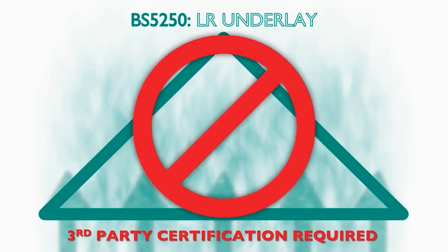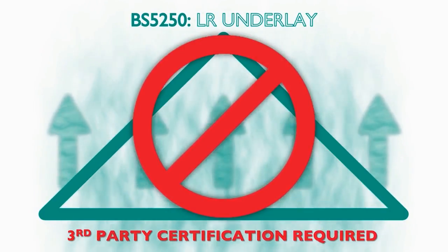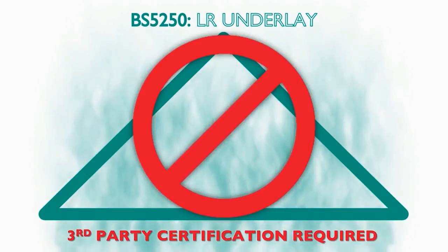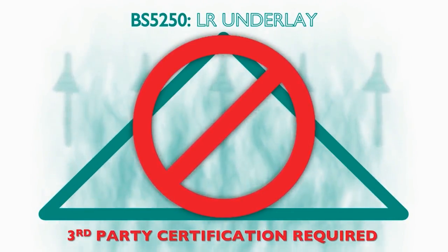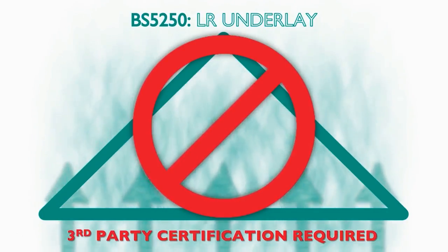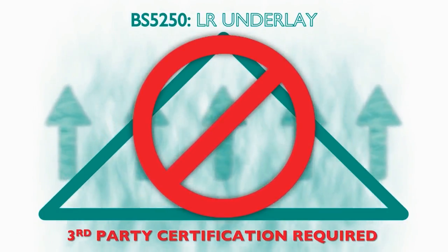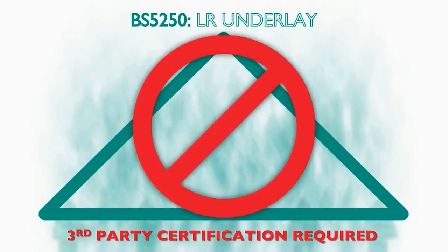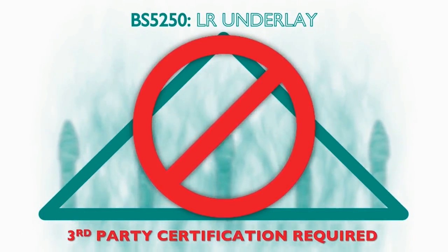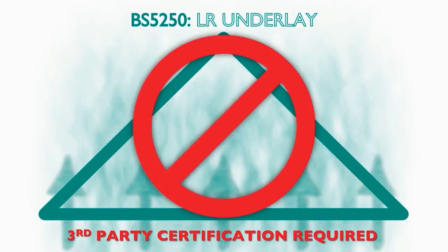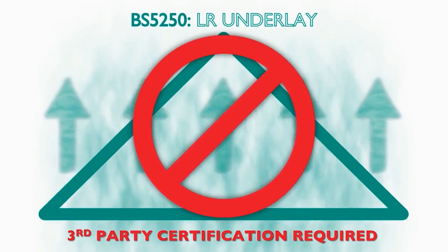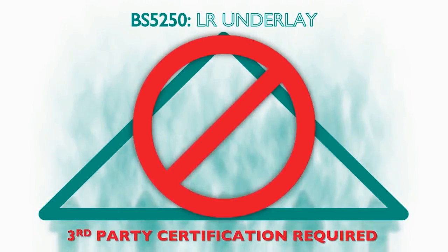However, as we've discussed, BS 5250 does not directly address non-ventilated roofing, and membranes used without ventilation must therefore be covered by third-party accreditation such as BBA, BM Trada, etc. Conditions for use of such membranes are given in these certificates rather than BS standards, and if ventilation is omitted, these conditions must be adhered to. However, it's not always quite that simple, as we shall see shortly.